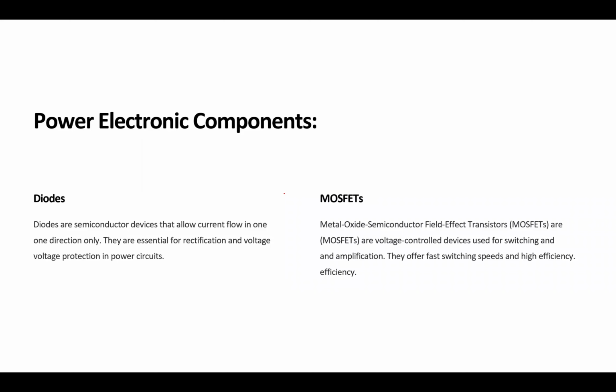AC to DC rectifying is the easiest. The easiest rectifier is a simple diode because it doesn't allow reverse current. If you apply AC voltage to a diode, it only allows one direction, either the positive cycle or the negative half cycle, to pass.